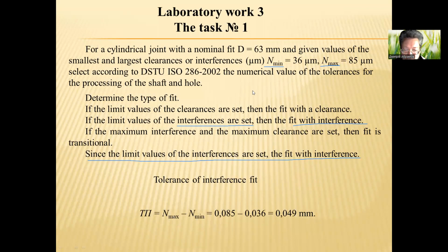Tolerance of the interference fit is equal to maximum interference minus minimum interference. We can calculate it: 0.085 minus 0.036 in millimeters, and we have 0.049 millimeters.